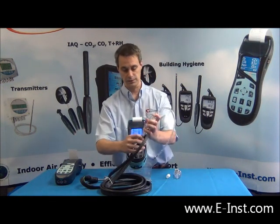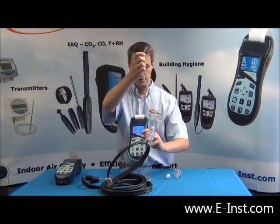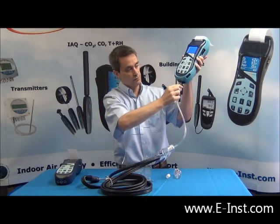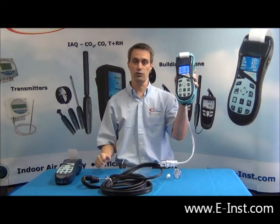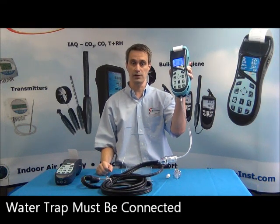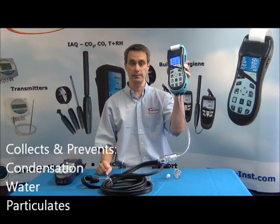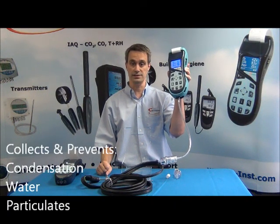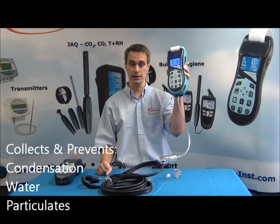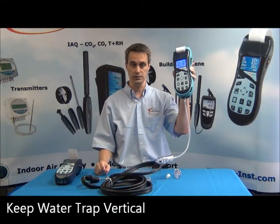Now you can plug the probe and water trap to begin the analysis. The water trap first connects to your bare hose on your probe. It also connects to the bottom of your instrument. The water trap must be connected every time you do an analysis, as it is an important part of the analyzer's performance. It collects and prevents any condensation or particulates from getting into the analyzer and damaging the sensors, pump, or internal electronics. It's very important to keep the water trap vertical at all times during use.